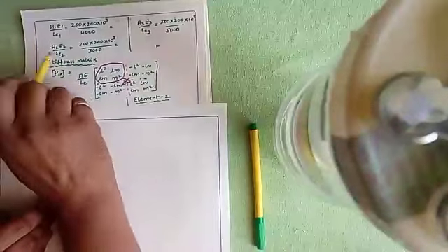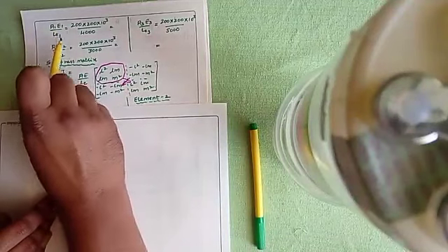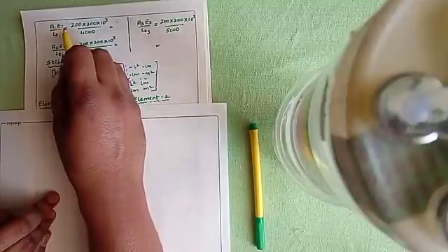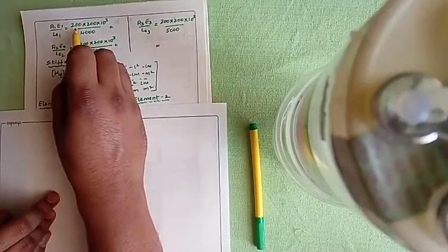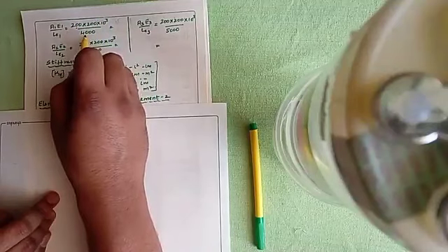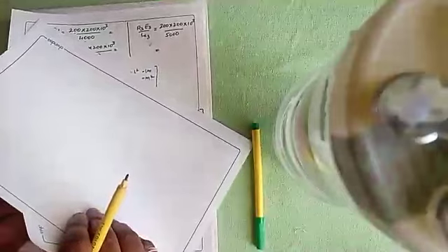Now, since we have three elements, we need to individually find out A1E1/L1, because if you do this, you can reduce your calculation steps. So A1E1 divided by L1. Area 1 is given in the question itself, that is 200 mm². So this is 200, and Young's modulus is 200 × 10³. Length of element 1 is how much? That is 4000.